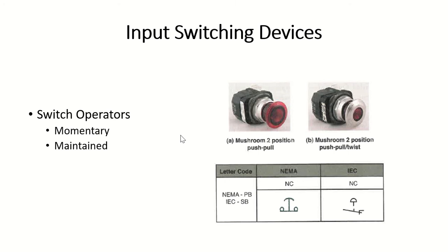their normal position. So momentary, again, I press it, it changes state, and as soon as my finger comes off that push button, the contacts go back to normal. Versus maintained, I press it in, the contacts change and remain in that position.